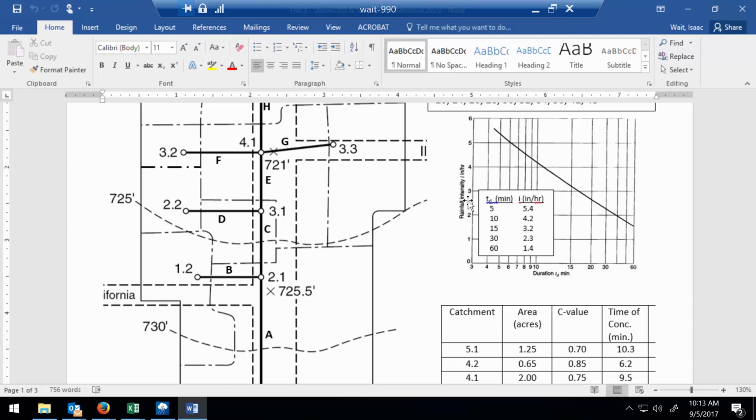And so here at junction 2.1, the water's actually coming from 3 locations as it enters pipe C. The water's coming from pipe A, which had an upstream inlet. The water's coming from pipe B, which has this upstream inlet. But then there's also, here at this manhole 2.1, not only is that a junction of 2 pipes coming in, but more surface water is also going in at that inlet. So it's accounting for all these things simultaneously.